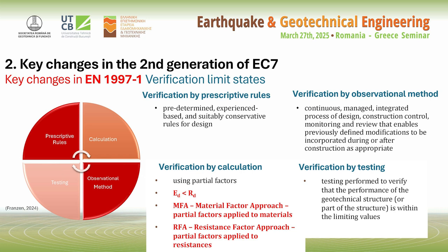For the verification by calculation, which is probably in more than 90% of the cases the method that we are using in our geotechnical design, now it's a little bit simplified. That means that we have one unique equation to verify, which is this one that you can see on the screen, Ed less than Rd. That means the design value of the effect of actions should be less than the design value of the resistance.